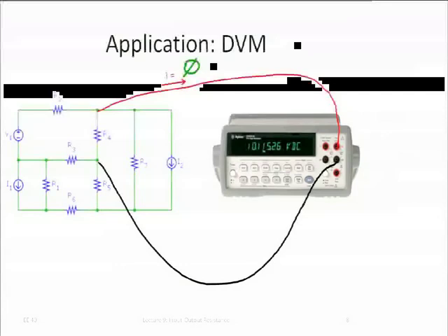Now, obviously, the internal resistance is 10 megohm. If you have a sensor that has much higher internal resistance, like a pH sensor electrode, then that may not be enough, and you get an error even with such a voltmeter. Incidentally, that's the advantage of these digital voltmeters: their internal resistance is very, very large. With the old analog ones, you actually have to supply enough current for the meter needle to move, so they have much lower internal resistance, a few tens of kilohms. So now we always use the digital ones. The analog ones you can hardly buy anymore, and they're very expensive. But the digital ones have very high internal resistance.